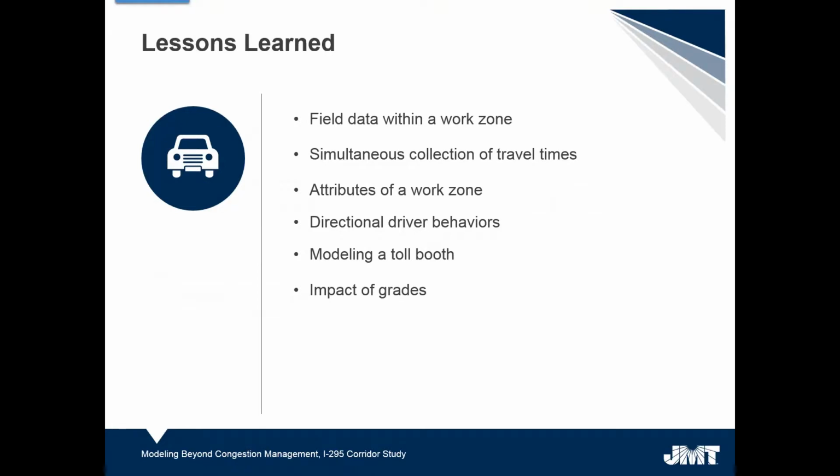So some of the lessons we learned as part of this project, I did already talk about the field data and how we found a workaround to collect it in the work zone. But another lesson we learned in regards to collecting data was travel time runs and how beneficial it would be to collect travel time runs in multiple lanes at the same time. Because this particular area has multiple lanes, each lane kind of operated differently. So if we are able to collect travel time runs in more than one lane at the same time, that would have been very helpful.